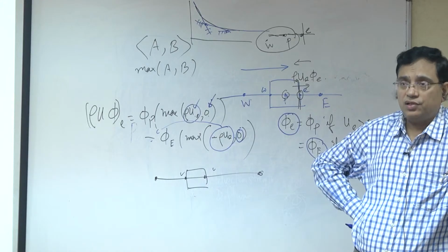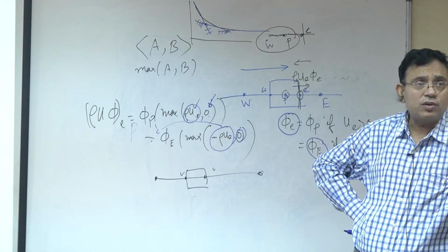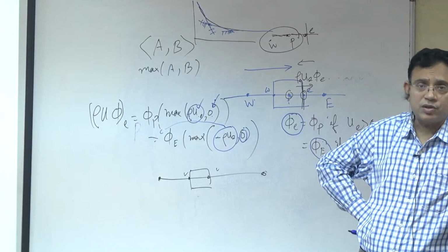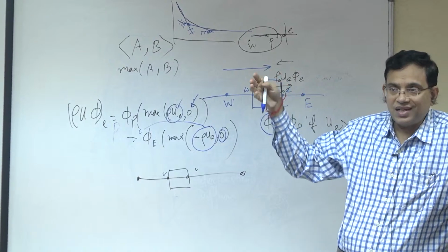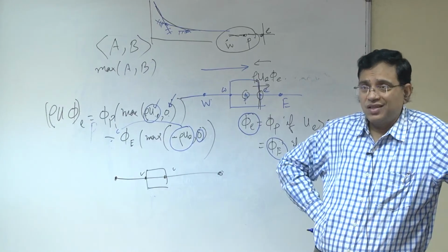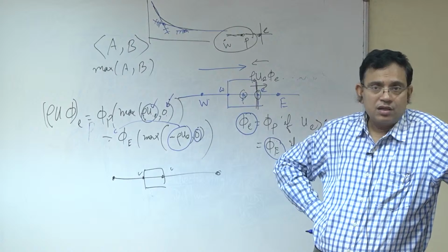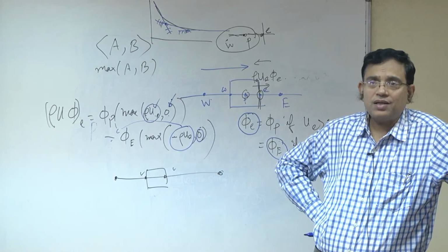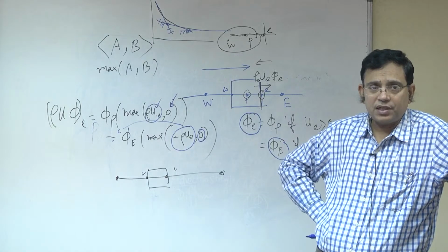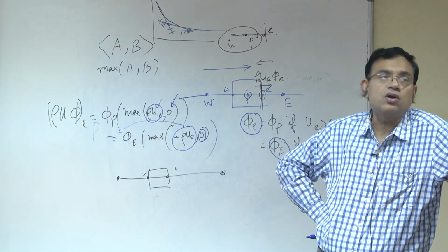So this is a representation of a complex function, not complex in the sense that it is really very complex, but complex to compute, by some simpler functions which are easier to compute. Maybe one such function will not do, but you can make a piecewise linearization and then combine it. Such a scheme is known as the hybrid scheme. But sometimes the exponential can also be represented approximately, not in e to the power form, but by a function with a certain power. That may give an approximation, and Professor Patankar found that with some value of that power it closely reproduces this one, and that scheme he gave the name power law model.